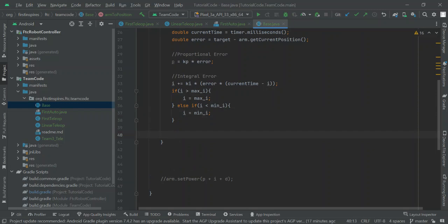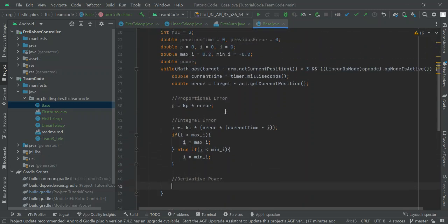One thing I'm going to say is that I would not recommend using the integral error. It can honestly just lead to a pain in tuning, and it does not improve the loops, and it has potential for messing up your loop. So I included the integral component in this video, but in future PID videos regarding movement and stuff, I will not be including the integral because it's not recommended for use in FTC just because it's small scale. The movement the robot does over the small amount of time is not really in need of an integral component.